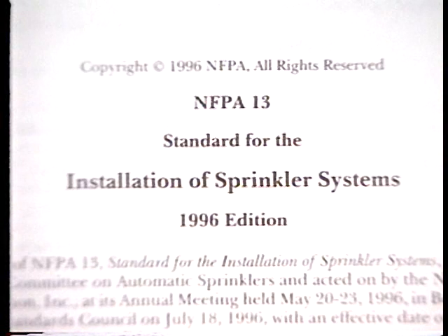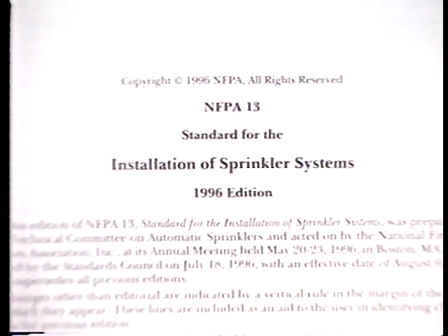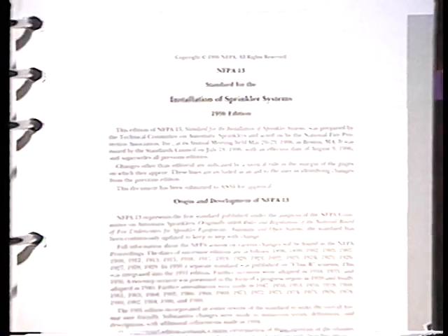These are considered special occupancy hazards by NFPA 13. NFPA 13 describes the methods of design, installation, fabrication, calculation, and evaluation of water supplies that should be used for the design of the system in accordance with the specific design criteria of the occupancy standard.